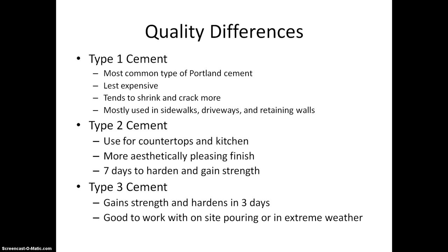Type 3 cement gains strength in 3 days. It's equally as strong as type 2, it just gains the strength quicker. And it's good to work with on-site pouring or in extreme weather where it's very, very hot or very, very cold, because that affects how the concrete dries.